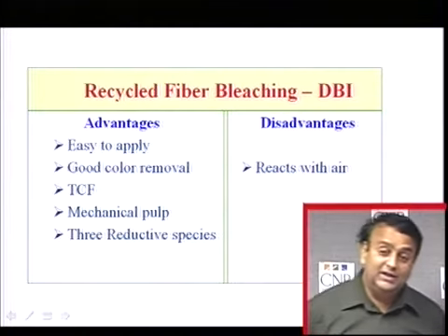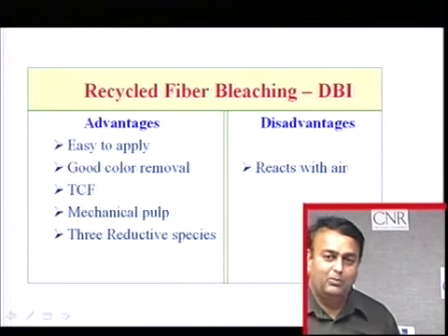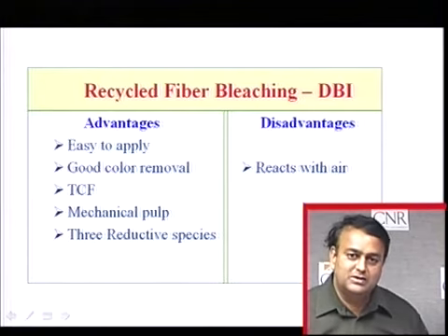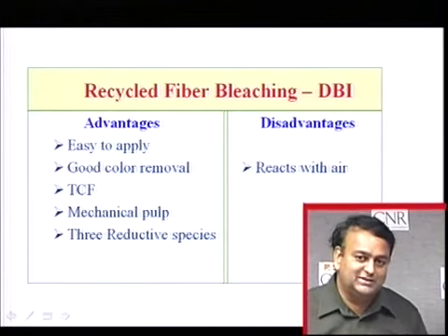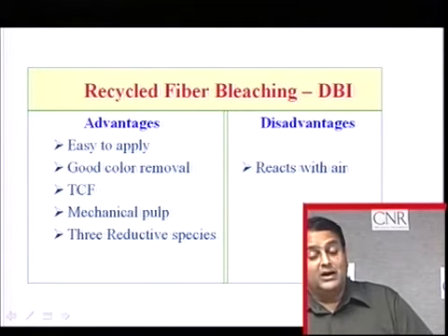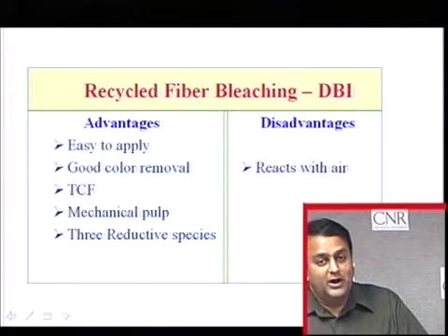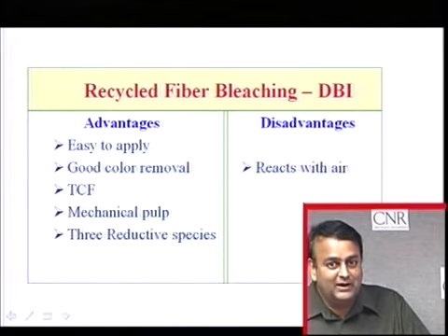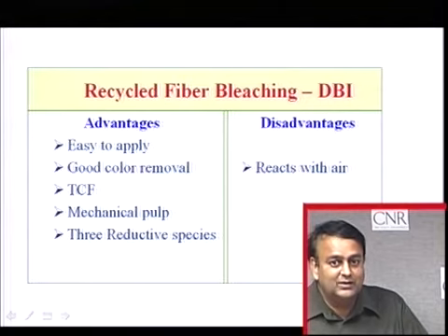What are the advantages of DBI? Very easy to apply, because these are two liquid systems. There are two pumps. You just pump it through the static mixer, and there it goes. Excellent color removal. Sodium borohydride is a very strong chemical. It attacks double bonds, particularly in dyes, and it works on those dyes and removes them.